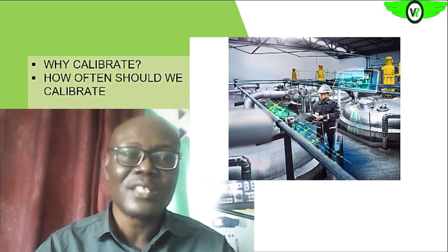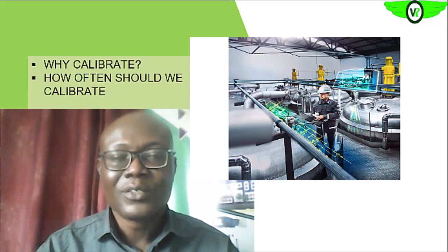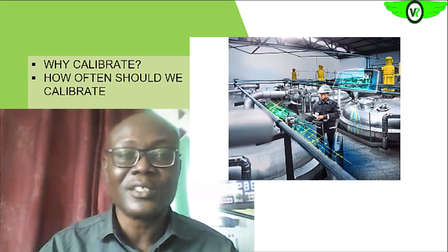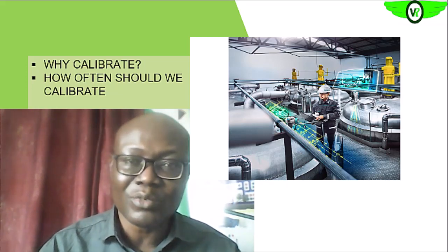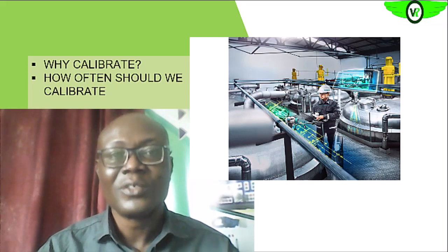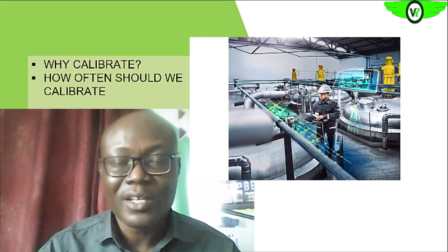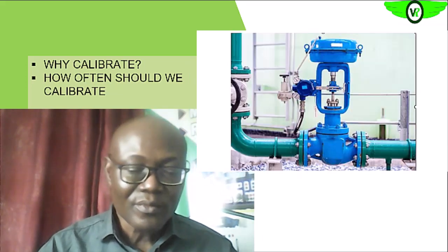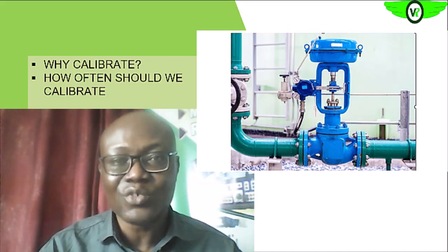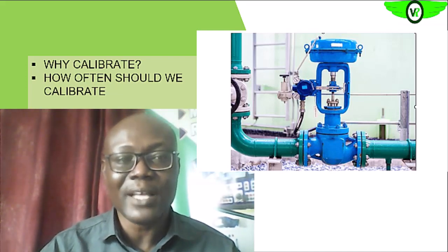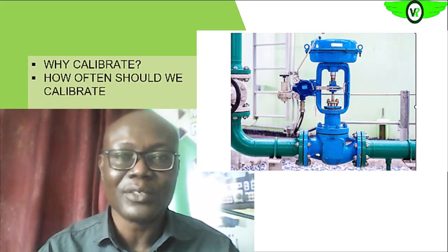So the next question is, how often should we calibrate? The frequency of calibration is determined by a few factors. The condition to which the instrument is exposed: if it is harsh, it means that the frequency will increase. Are we getting it? And of course, the frequency of use of that particular instrument also determines the frequency of calibration.